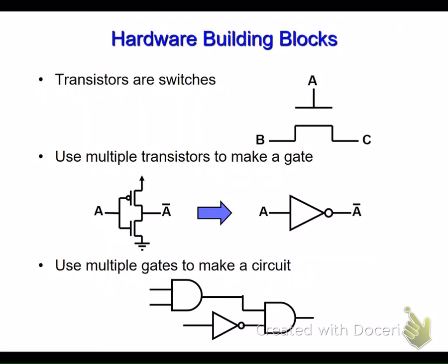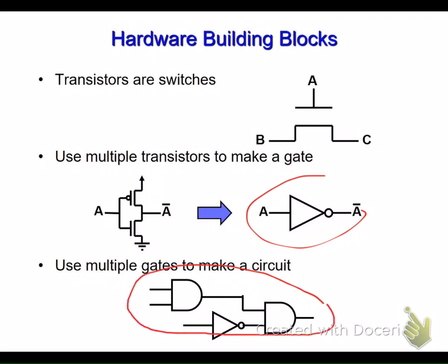So these are the hardware building blocks: transistors, or multiple transistors. In the end, you will have gates, or multiple gates. As an example, you might have a library in your tool from which you can grab a component like that. As I mentioned earlier, in Quartus 2, for example, you can grab such a component if you design by blocks. But when you go to Vivado and want to transfer your design, Vivado will not be able to transfer this because it's not in their library, and they will not be able to automatically replace it with whatever is in their library. But if it is written in Verilog or VHDL, it will be a smooth transfer between the tools, as we mentioned.